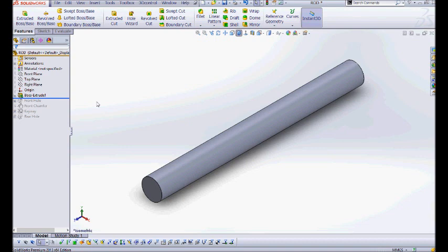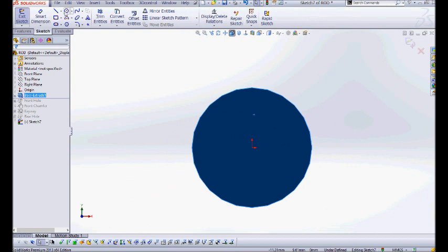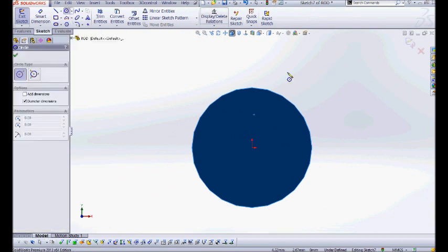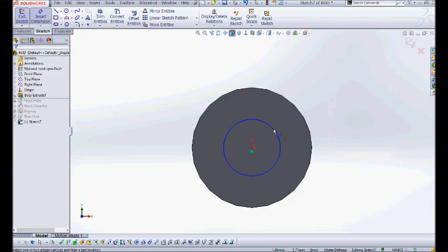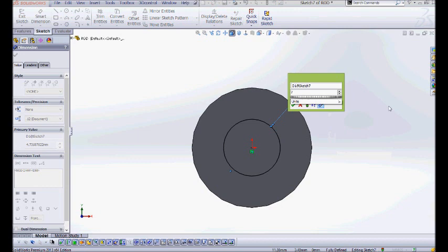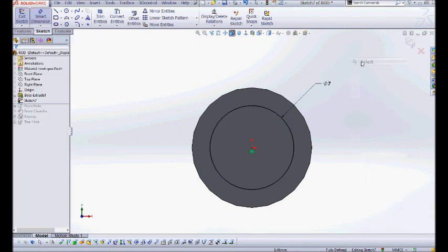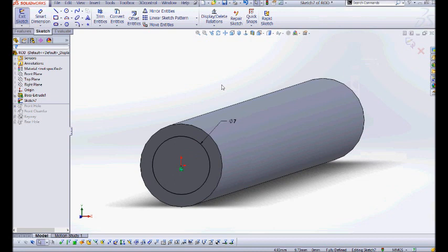It's not fully defined. We need to recenter it. We're also going to change the size from 3 millimeter to 4 millimeter. So how do we do that? We're going to highlight the hole and select Edit Feature, right here where it says Edit Feature. That'll bring the hole wizard back up. We're going to change the size to 4 millimeters, and then go over to positions.